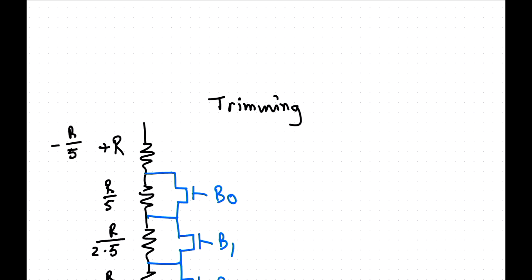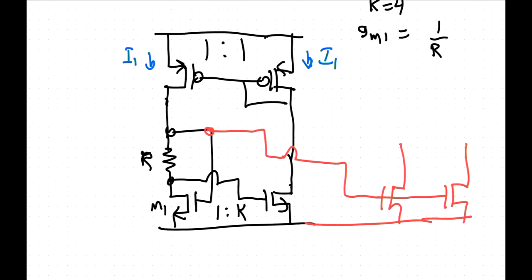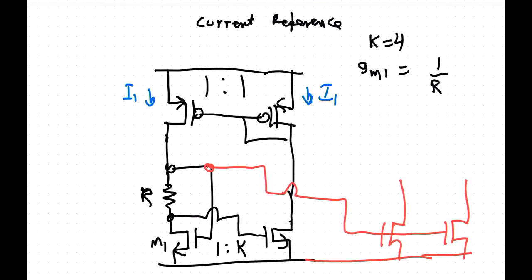All right, I should probably also talk about bank of references, but we're running out of time. I want to say another thing about this one here, actually, what is important, and that is that this circuit in itself actually has two stable states. You've got one stable state where you've got 0 volts here and here, so there's no current. And you've got VDD on this node here, so there's no current.